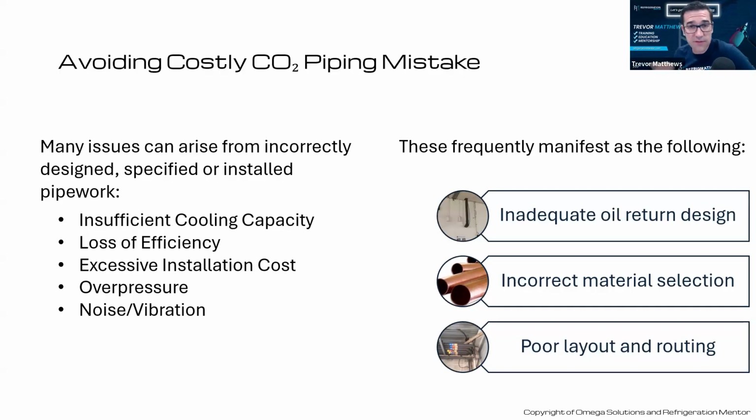Because here in Canada, you have to use stainless steel. Yeah, you're not using any high pressure copper on the discharge lines. Definitely. Again, where you are in the world will depend on that. Because in the UK, we can use K65 on the high side, but it has to be rated at 120 bar pressure. Whereas normally we'd also get 80 bar pressure pipe, which we'll happily do the sales for.